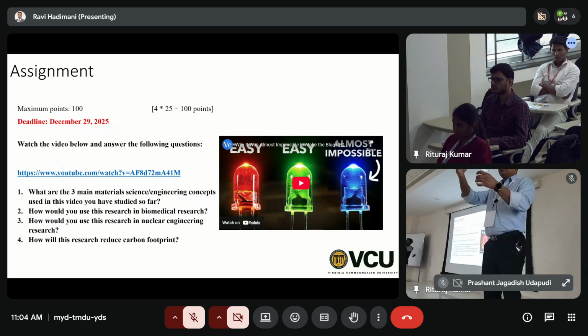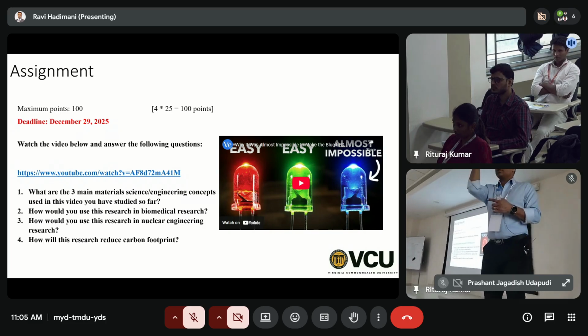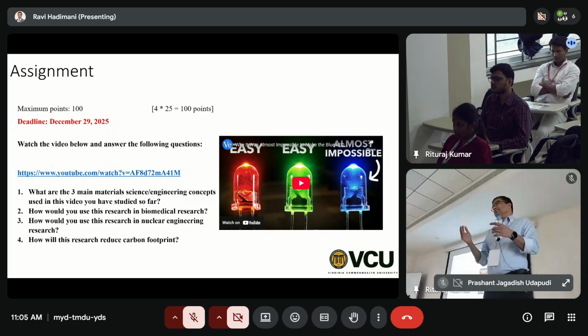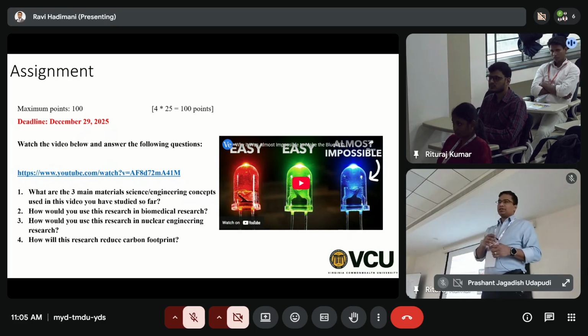If you are doing a tool bit, a drill bit, it has to be mounted this way, right? And for that, some physical vapor deposition methods will not work, because they won't deposit on this side. So it's constrained by your application rather than whether it's PVD or CVD. And the other problem with CVD is you have to have metallic gas.